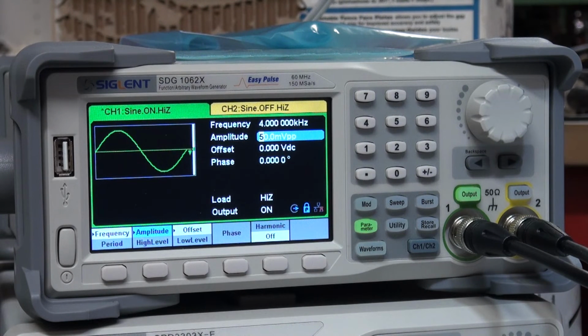And for low level signals, the amplification will be dominated by the ratio of R1 to R2. As the input signal rises, the output signal will get larger, and the OTA gain will increase, but since it's in the negative feedback loop of the op-amp, it will decrease the gain of the op-amp.